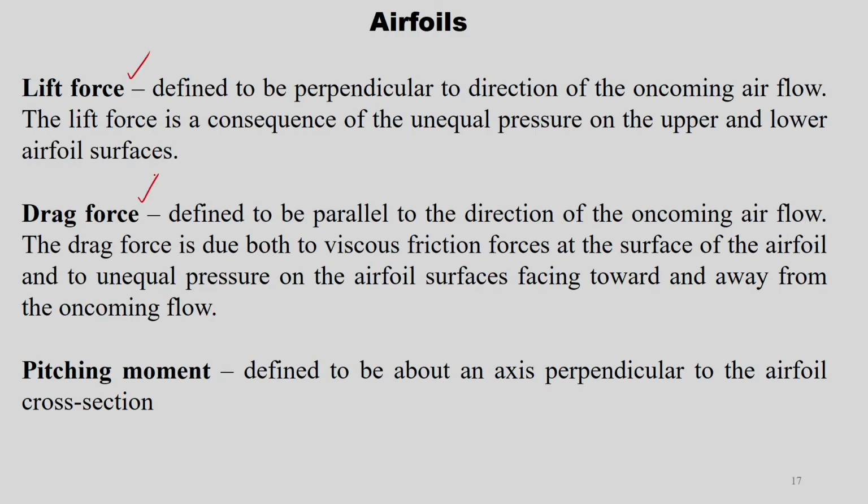In airfoils, lift force and drag force I already explained to you. Lift force is perpendicular to the direction of the oncoming airflow, and it is also a consequence of unequal pressure on the upper and lower airfoil surfaces. Opposite to that, drag force is parallel to the direction of the incoming airflow, and drag force is due to both viscous friction forces at the surface of the airfoil as well as unequal pressure on the airfoil surfaces facing toward and away from the oncoming flow.